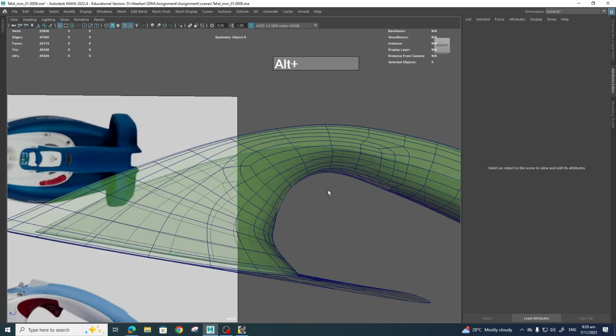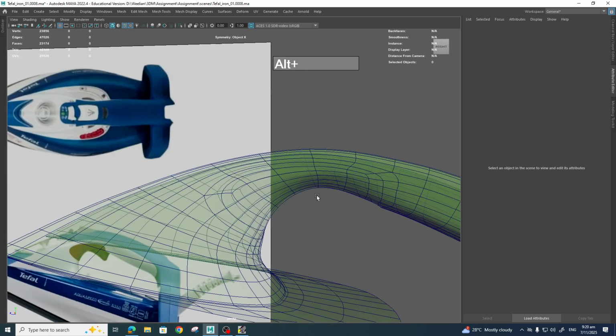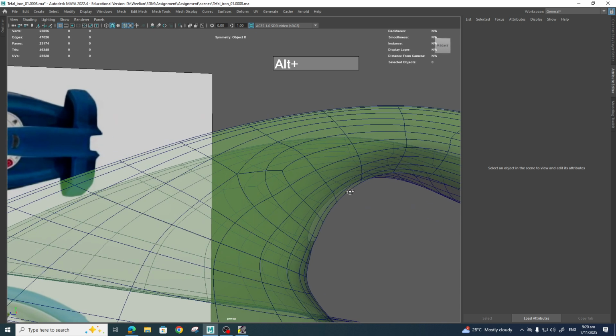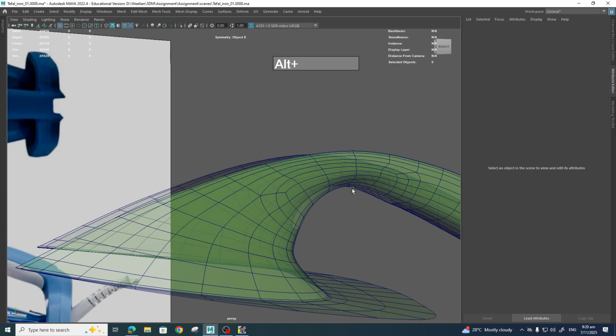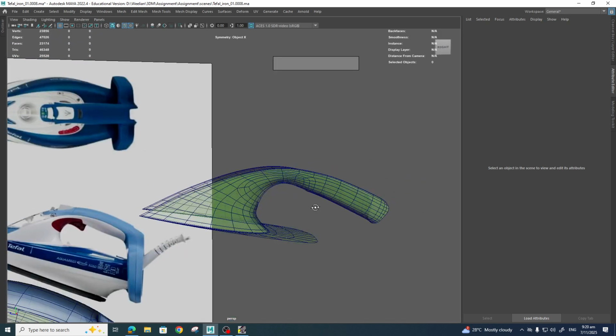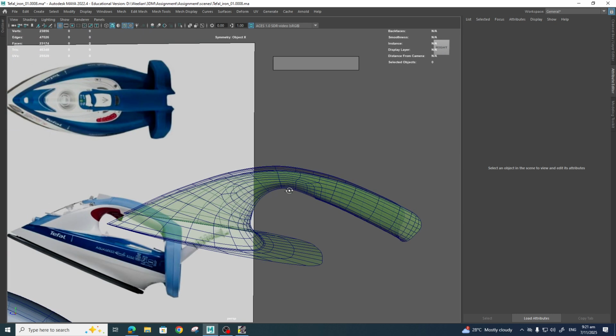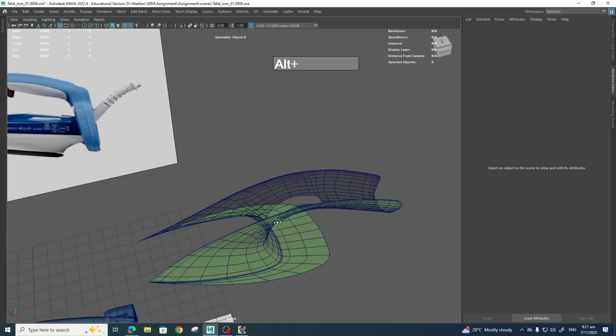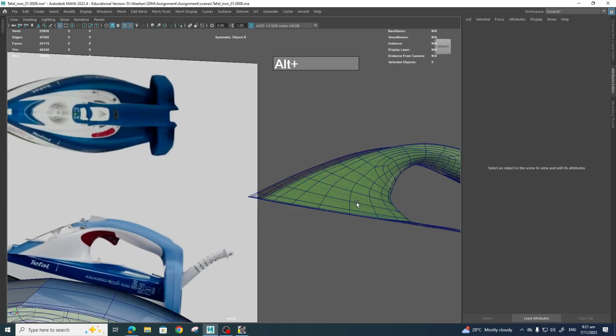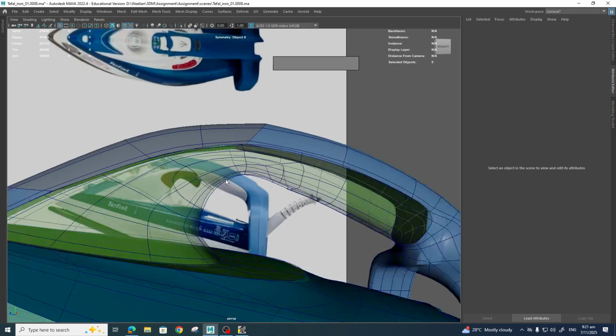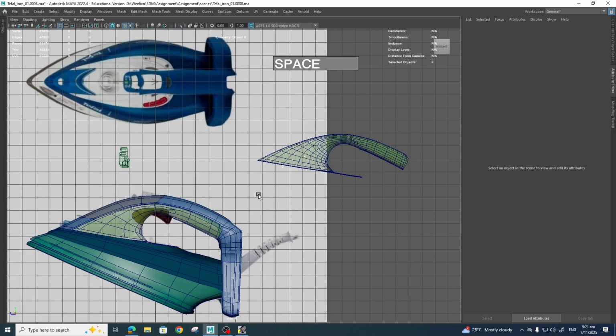Okay, 1 division is good enough, and we'll see how it looks. So we ended up having this, we still get this nice topology over here. After we smooth it, everything will still be converted into 4-sided faces. So I think this is fine. We're going to leave this as a multi-sided face for now.